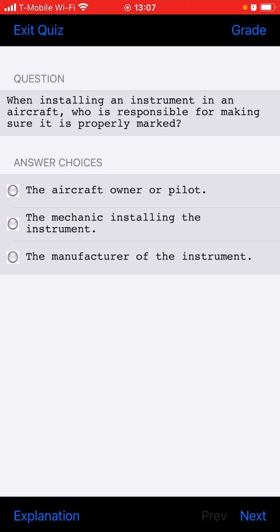What condition should a mechanic look for during regular inspection of an exposed piston section of a landing gear? He should be looking for whether it's clean, evidence of damage, or the proper extension. What prevents the air from leaking out between two halves of a split wheel assembly? An O-ring.